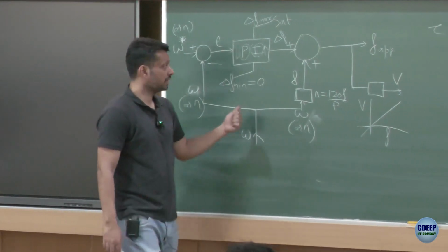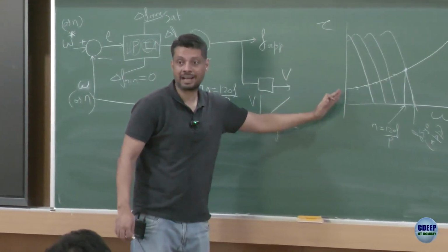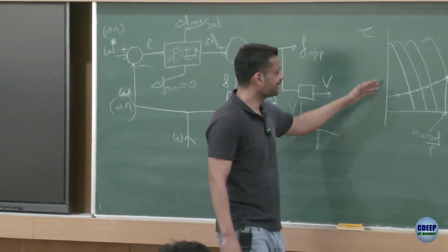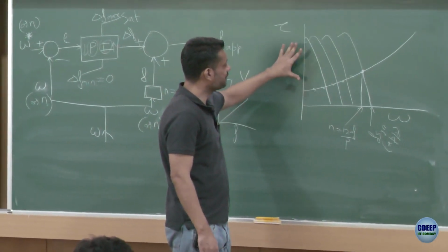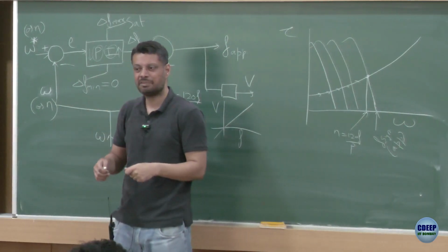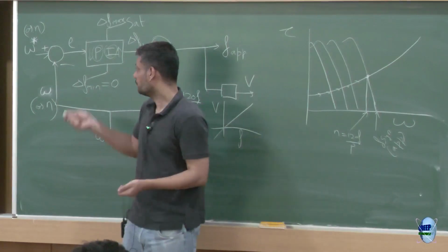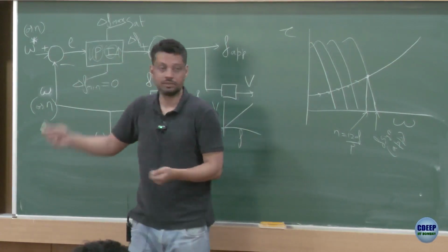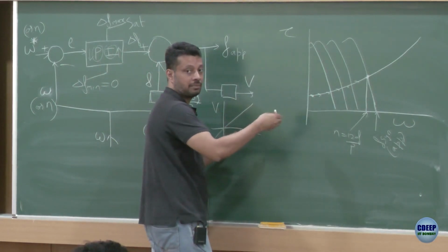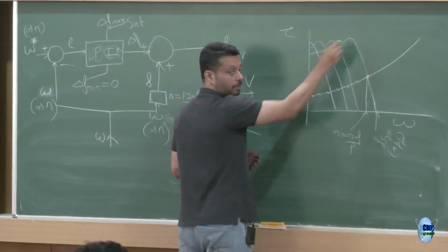Let me tell you why you require saturation. So, initially your speed was 0, right? Your reference was this one and you were accelerating. Anyways, your speed is increasing. But then let us say your PI controller is relatively fast. So what will happen, your speed is increasing slowly, but this guy is really excited. So it will keep on increasing delta F very fast. So even though you are somewhere here, in that short time this guy can take the delta F to such a large value that your characteristic is this one, the last one.